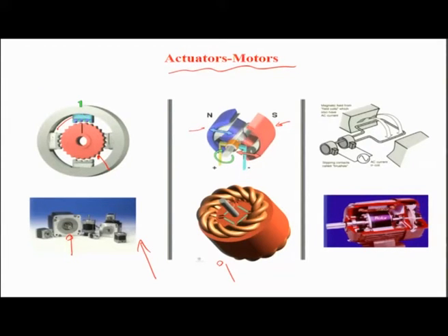There could be an AC based signal given to a magnetic coil in a fixed magnetic field, and the AC signal would ensure that the current directions alternate, because of which there are differential Lorentz forces on both these components based on the static field, and it will allow motors to rotate. The contacts in such cases are given through contact brushes, which form the basis of feeding the coils in the rotor. So these are some of the actuators which would be conventionally used to create motion.